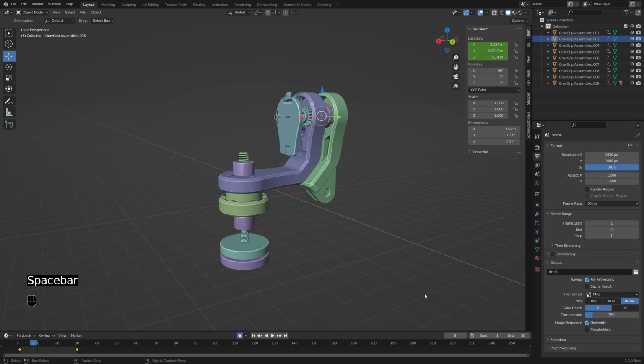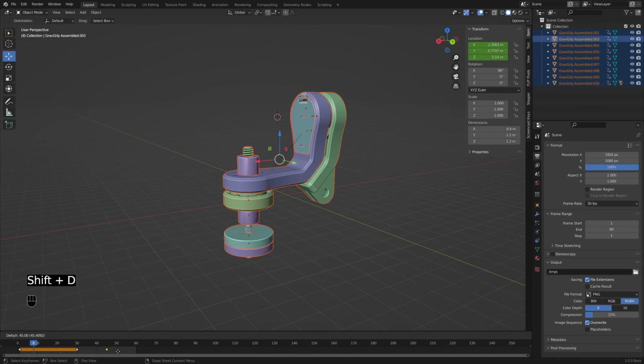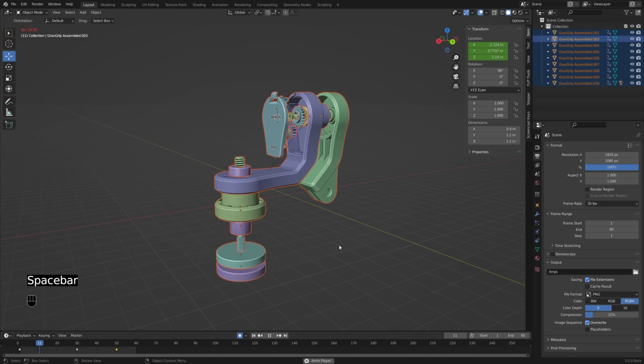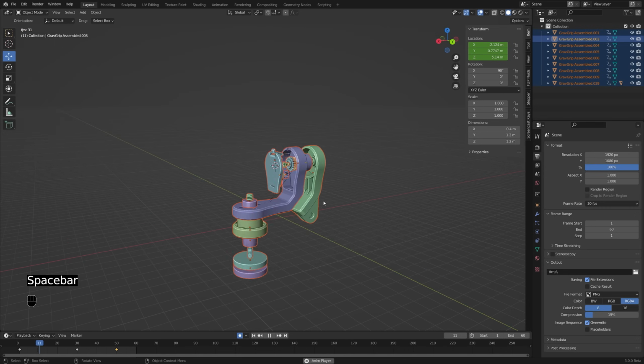So working easily. If you wanted to have it come back together, let's just give ourselves some more frames. This is kind of an odd thing happening down there. It's like kind of flashing. So I'm pressing C to circle select, and that's just selecting. Okay, I want to make sure I have all my objects selected, and then C to select all of those. Shift D, and then let's say maybe it only takes 20 frames to get back together. So our whole animation is, well, we'll leave it at 60 so it kind of pauses for a second.